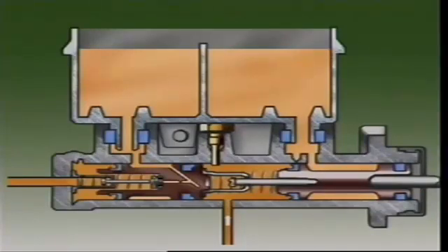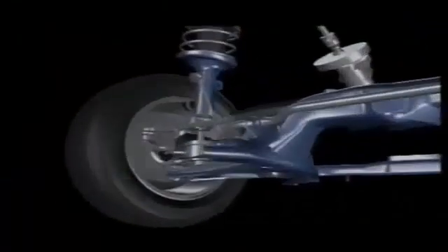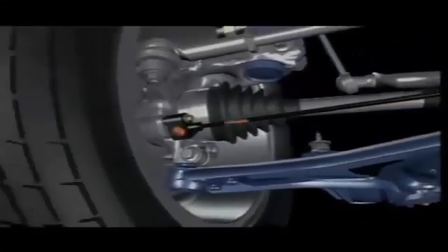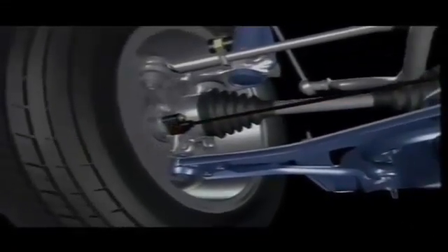The amount of fluid that returns to the master cylinder is determined by the degree of anti-lock braking control. With approximately 4 to 6 ABS control cycles per second, the rapid changes in pressure cause pulsations that can be felt by the driver at the brake pedal.